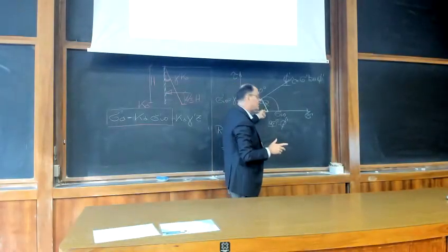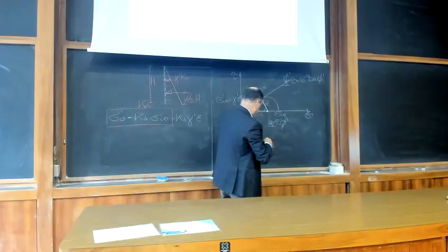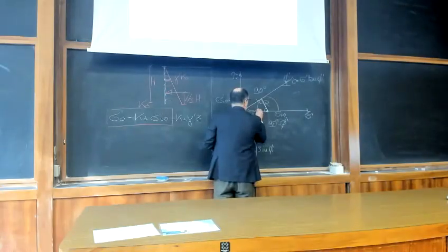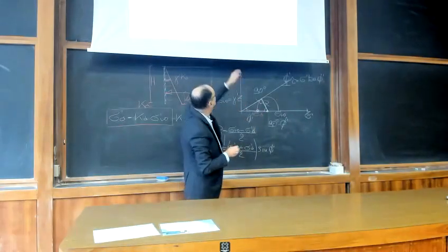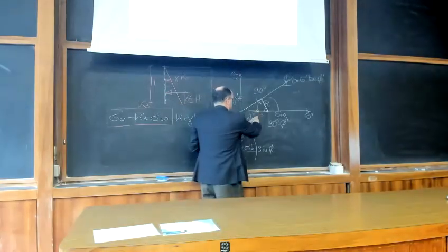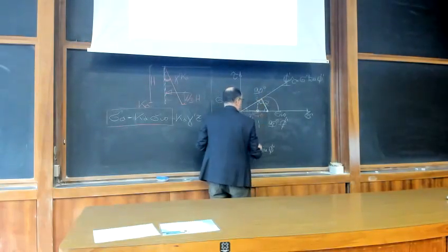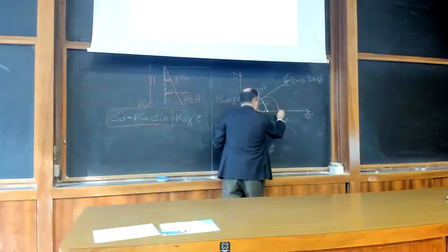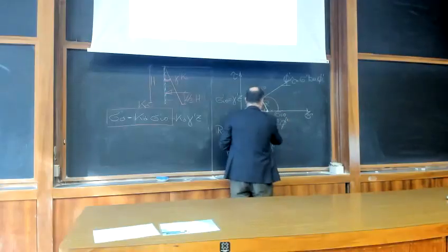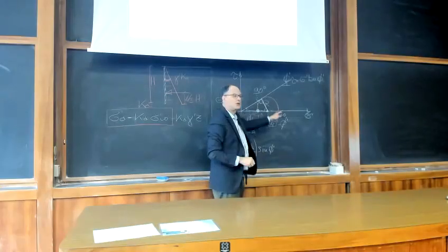Now we can go back to this figure and think that this is the pole of your circle, the origin of planes, okay? Because this is the horizontal stress which acts along the vertical plane, and this is the vertical stress which acts along the horizontal planes. So you can easily determine the origin of planes of this Mohr circle at this point.